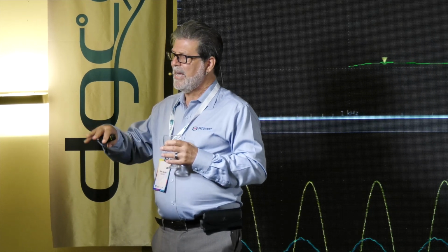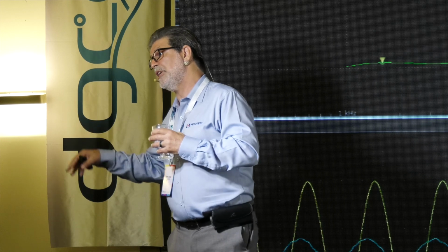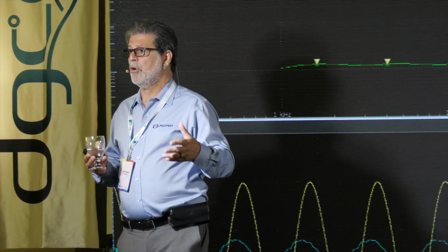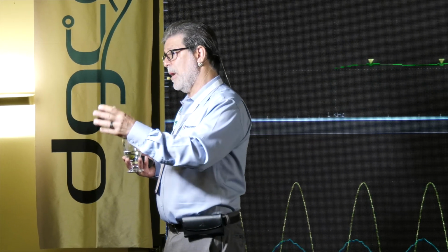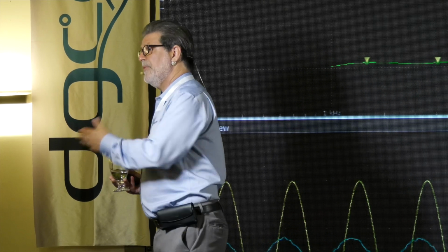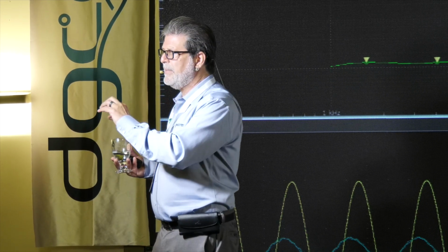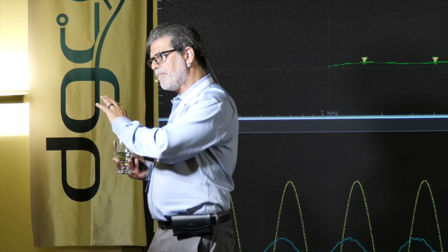Now, you're right. As I raise the resistance, it's going to be more susceptible to current. Those current changes are going to induce voltage changes. And in very simple terms, the total noise of the chip is equal to the product of the dynamic current and resistance plus all of the other noise sources, right? And when I add all of those up, they all need to meet the chip requirement.